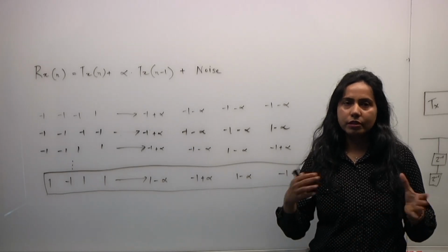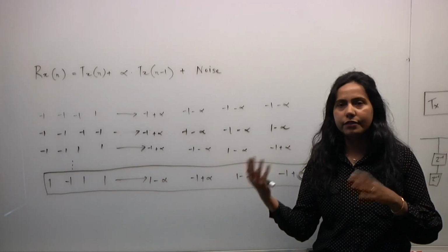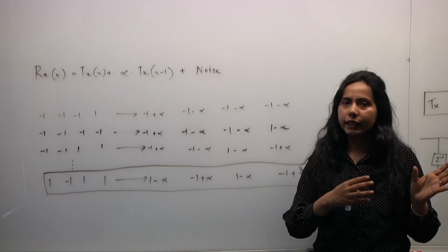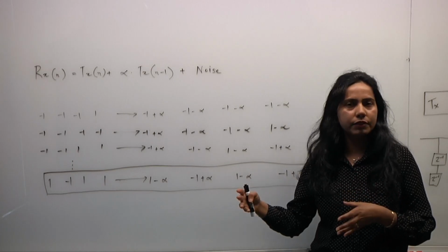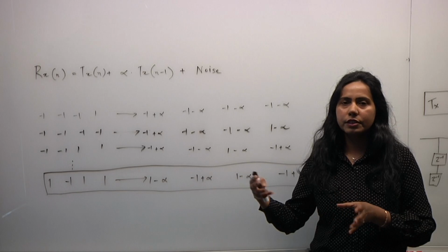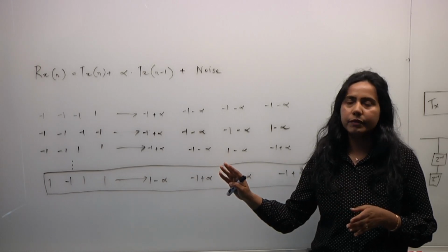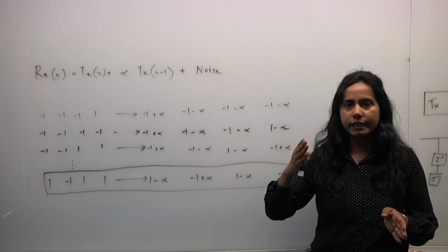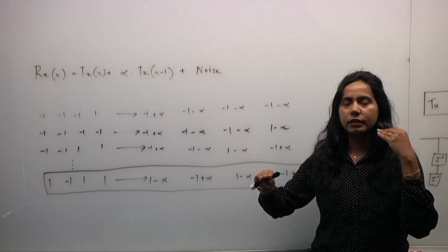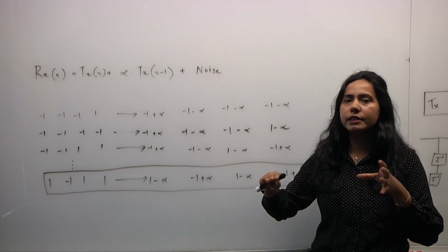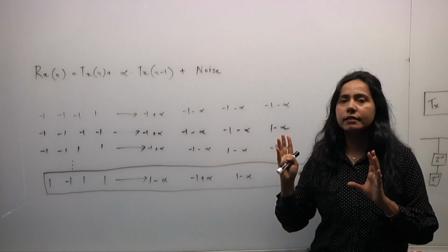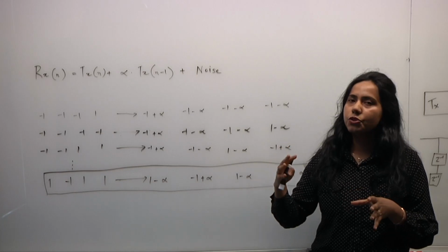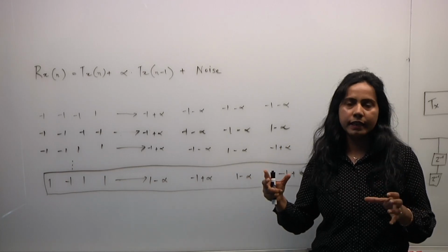Right. So we talked about the conventional DSP, which is your feed-forward equalizer and your decision feedback equalizer. With the feed-forward equalizer, you kind of clean out the inter-symbol interference, and then with the DFE, decision feedback equalizer, you completely remove that ISI. What MLSD does is it's basically a separate data path right after your FFE. Instead of completely removing the ISI from the data, it's not seeing ISI as noise. It's thinking of ISI as depending on the transmitted sequence, and it's trying to leverage the energy from the ISI and boost the signals.